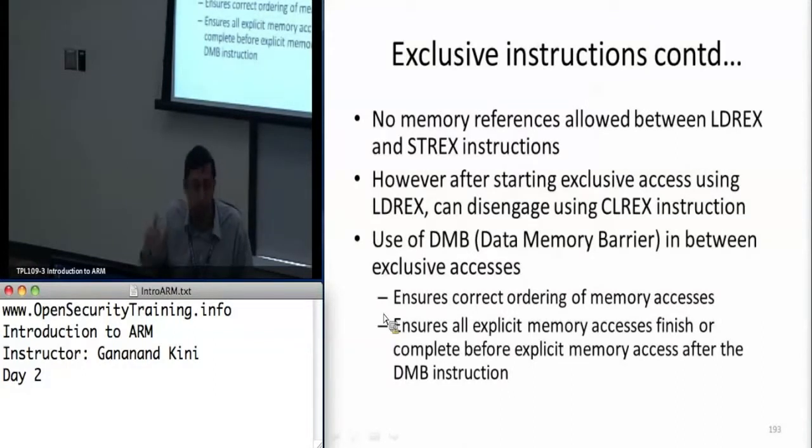So the memory barrier is only applicable to the processor that it's running on, and other processors could technically continue accessing their registers, or they could access this core's registers. This is used mostly on the one core of that one processor.